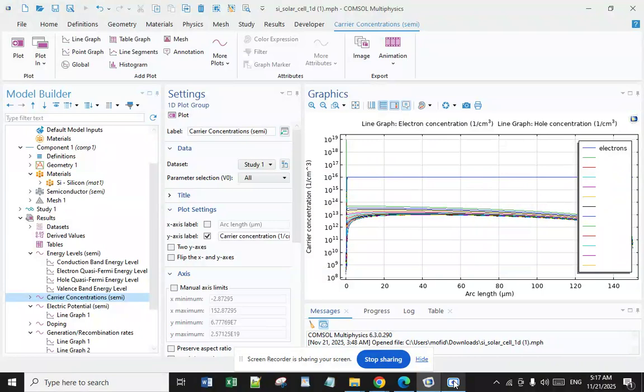And what about the causes and characteristics? The first is minority carriers. Leakage current is primarily due to the flow of minority carriers across the p-n junction. And the next one is temperature dependency. It increases significantly with rising temperature as more minority carriers are generated.